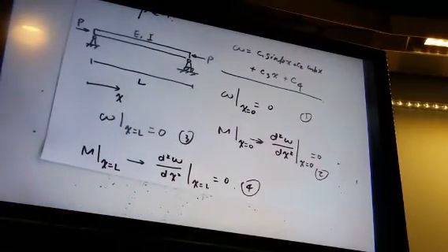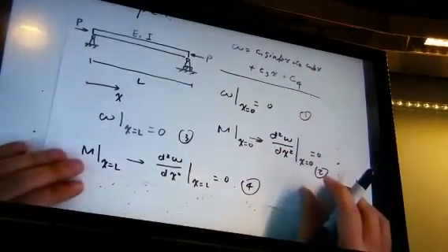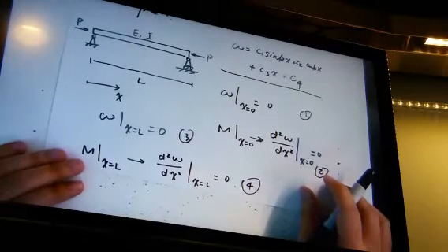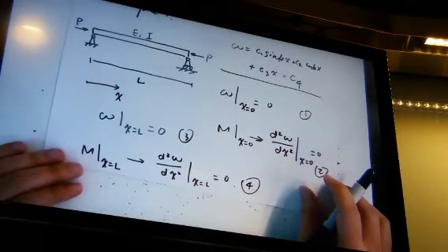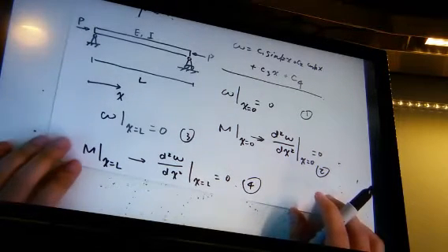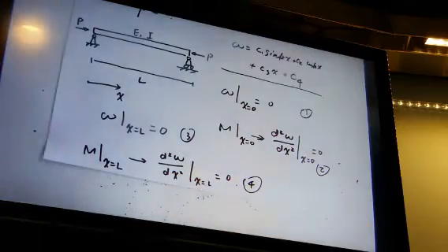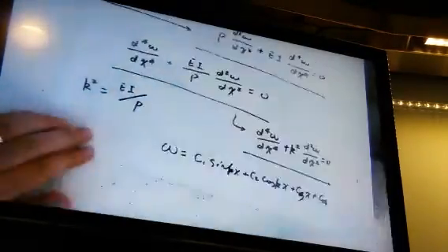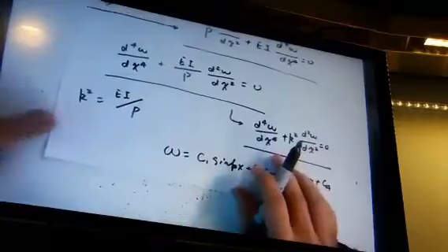And we derived it from the balance equations, force balance and moment balance. Okay? The first step is to plot a free body diagram, and then do moment balance and force balance, and then you can get the governing equation. The governing equation is here. This one.